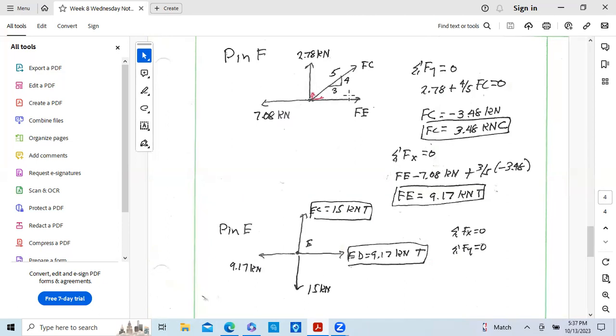And choosing tension, this is also positive. So vertical Y is 4/5 of FC equals 0. So FC also comes out to be negative 0.48 kilonewtons. Again, I draw the red, indicating it's compression. I'll label that back on the truss that we're looking at.